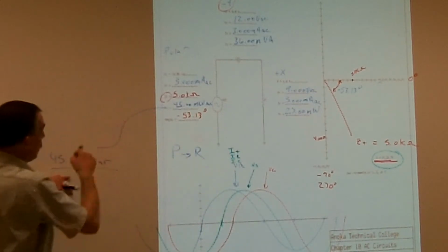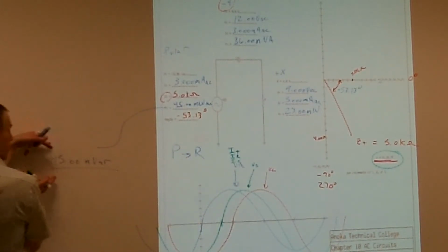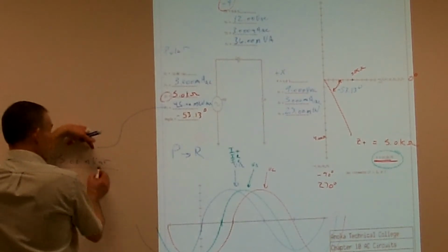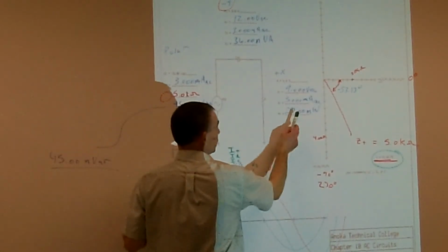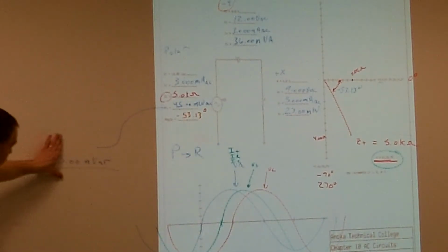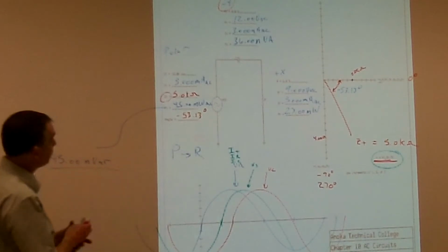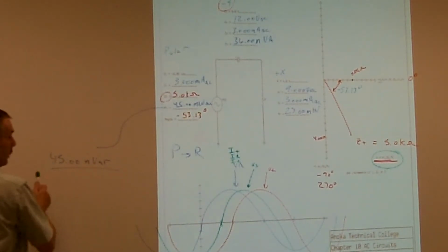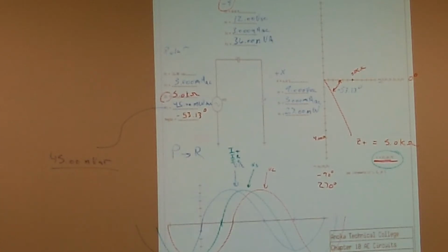The remainder of it is all the reactive power. So the power company is going to charge us for 45 milliVA, though we're only actually getting 27 milliwatts out of our circuit. But we get charged for the 45. And those are volt-amps, always calculated using the RMS value.